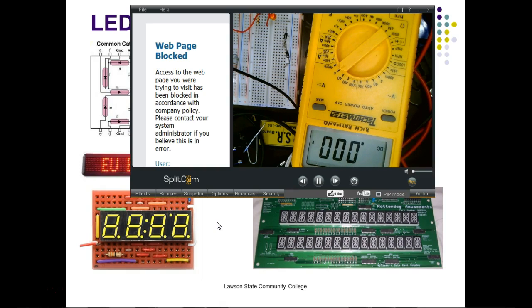So your old ones, if you look at the difference in size, your fluorescent LCDs had to be big because they had to have what behind there? They had to have that fluorescent bulb. Your LEDs are going to be really, really thin now because why? Because they're backlit by LEDs. So this is an LCD screen. It's just that it's backlit by LEDs, and that's why they call them LED screens.